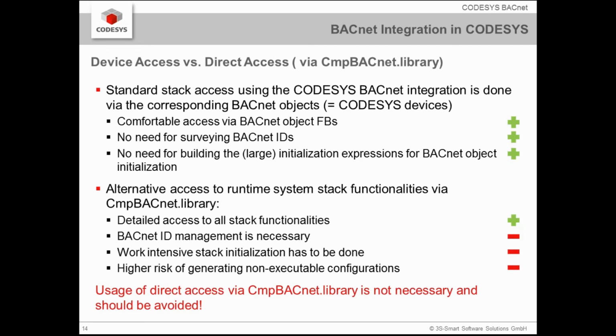Let's talk about accessing the external stack. In general, with the CODESYS BACnet integration, there are 2 ways of accessing the external BACnet stack. The standard way of accessing the stack is using the BACnet objects, which are represented as CODESYS devices. There are different advantages to this way, so you really have comfortable access via BACnet object FBs, function blocks. There is no need for surveying BACnet IDs, and there is no need for building large initialization expressions for BACnet